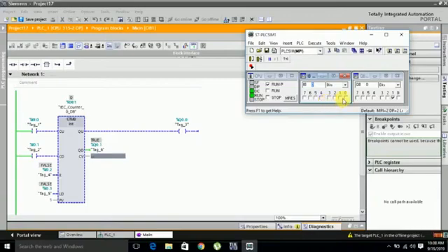So first we will see counter up. You see here it is 0. I will use counter up; counter down is already enabled at 0. But when I count up, the value is 1 and the output is also off. Let's see, first counter up: 2, 3, 4 and 5. This output is on.